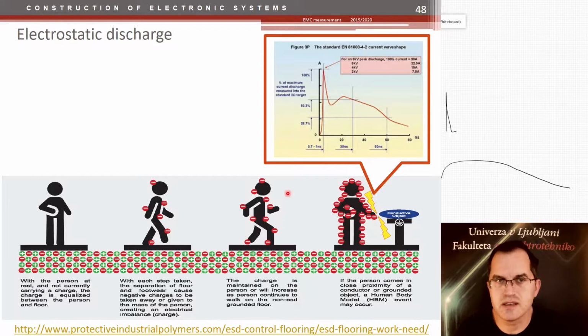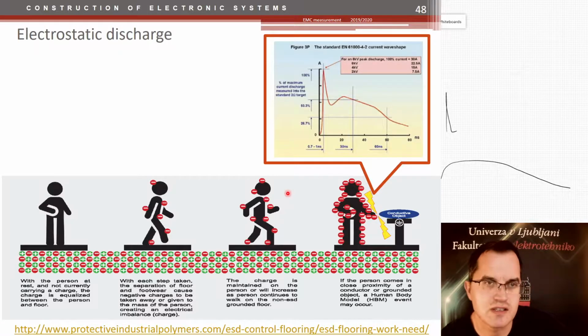If the resistance is too low, it's dangerous for you, because you can get killed. If it's too high, then it's dangerous because of the ESD. So you have to have a certain resistance value which is just in between. And I'm still talking about mega ohms, not kilo ohms or tera ohms.